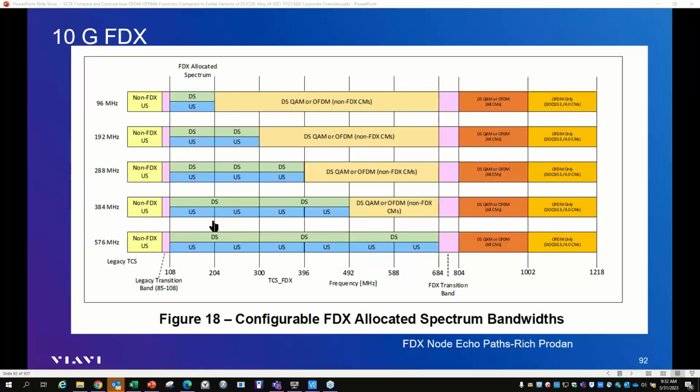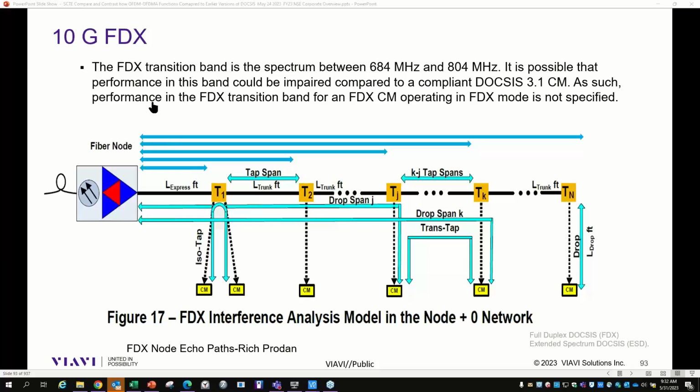So that means that the CMTS will have to control traffic based on the requirements on the downstream, based on the requirements that the customers require on the upstream, as we start to segregate the downstream portion of this in order to start to deliver these types of services, right? So if 10 gig symmetrical service is the requirement, think about this concept, right? So again, extending the bandwidth to 680 megahertz, and then deploying the rest of the single QAM carriers above, all the way up to 804 megahertz.